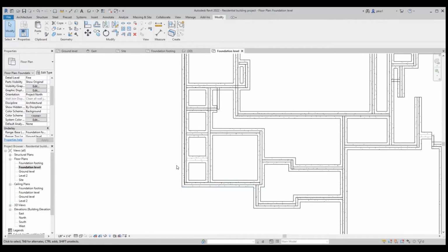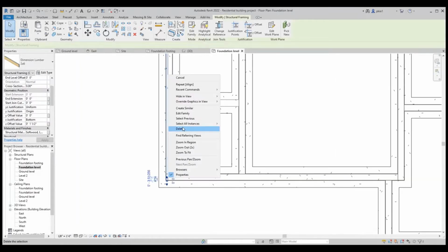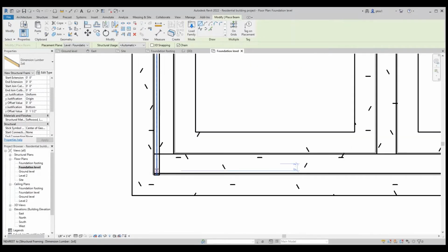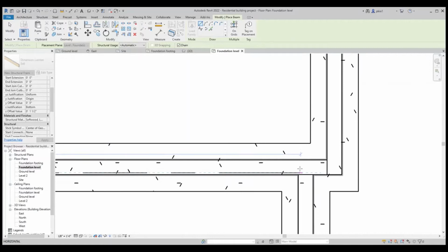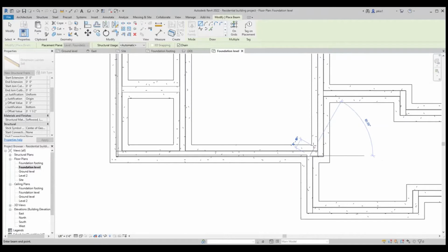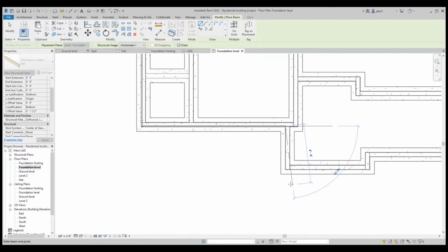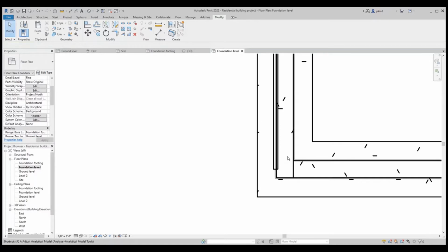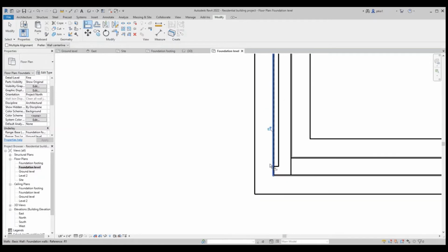In this way now, escape from the command, select the wall and say create similar. And we can put it at every wall, every perimeter wall, exterior wall. We can draw this and then, okay, this is neat enough. We can draw at each perimeter wall. But this would have to align AL, and then we select this edge and this edge, so it goes back in.